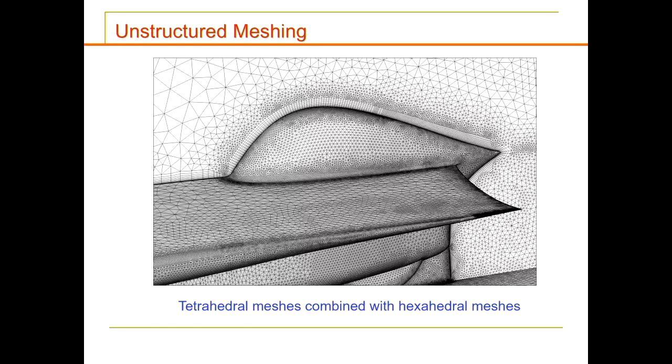But beyond that, I can just do a triangular mesh if I'm not really concerned about the characteristic of the flow there. I'm more concerned about the flow around the body itself.